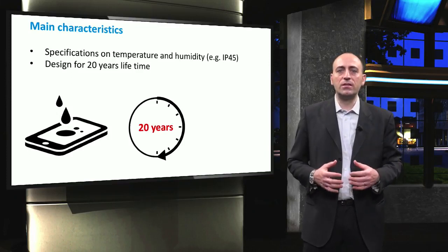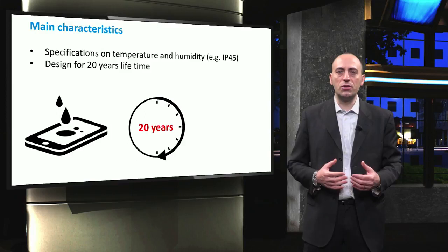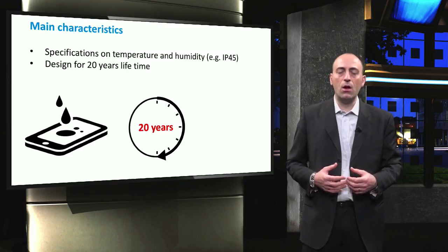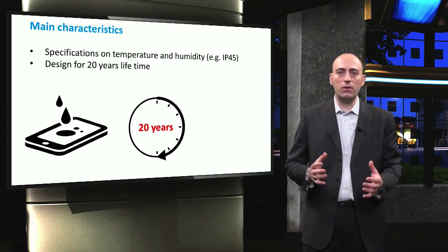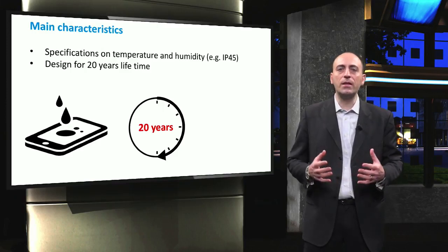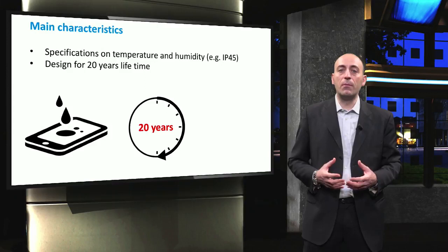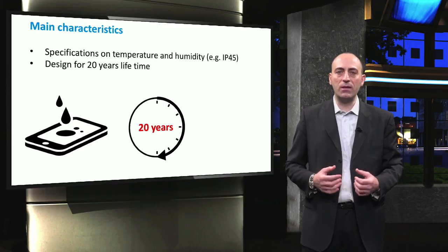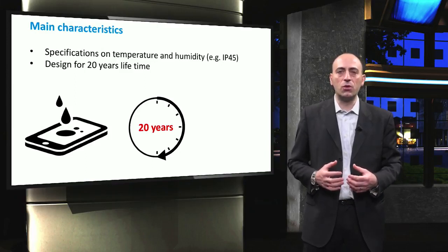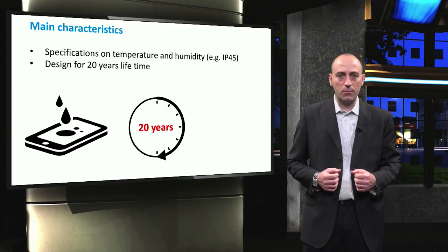Usually, the device has to be designed for high ambient temperatures and 20 years of operation, although most of the time brands offer warranties ranging around 15 years. Nowadays, these components are becoming more and more reliable, but power electronics and batteries remain the most fragile part when it comes to maintenance, while PV panels are usually the sturdiest part of the PV system.